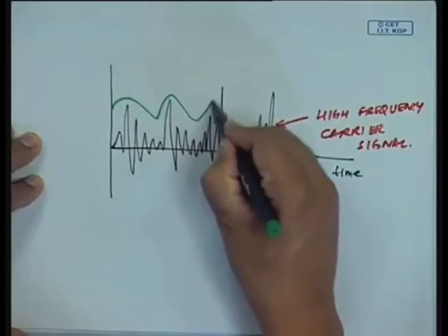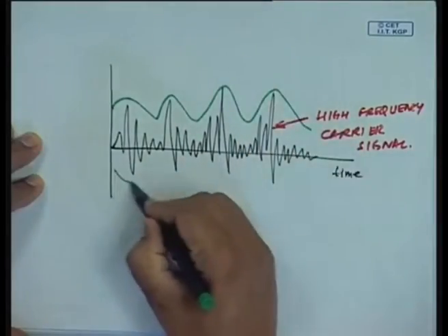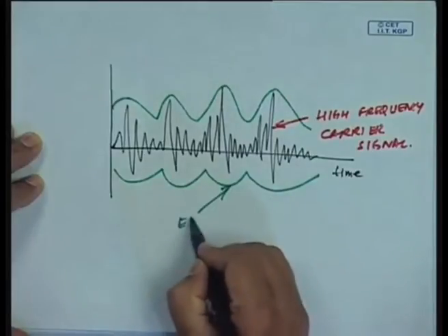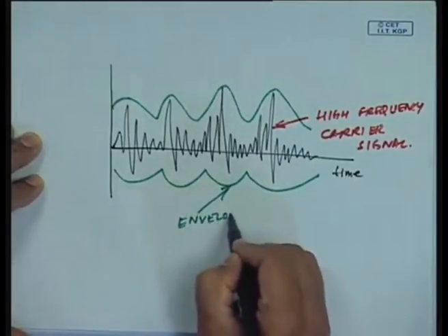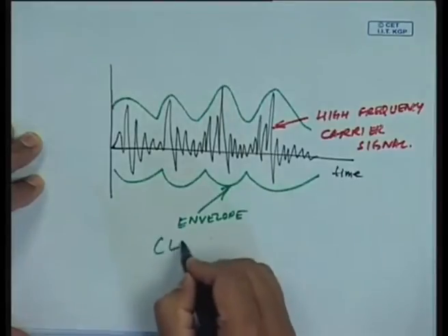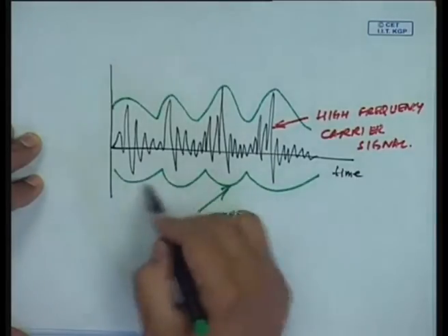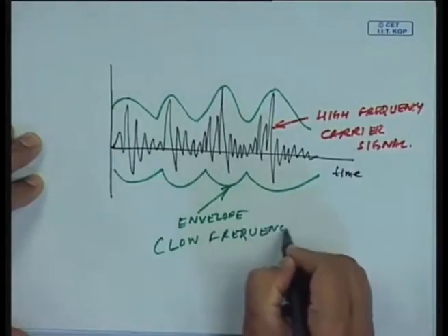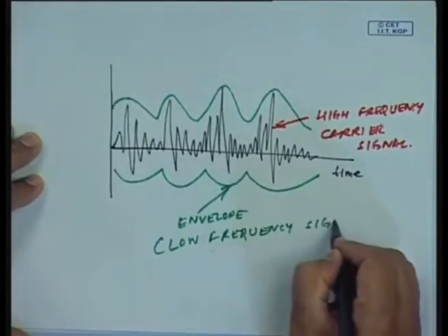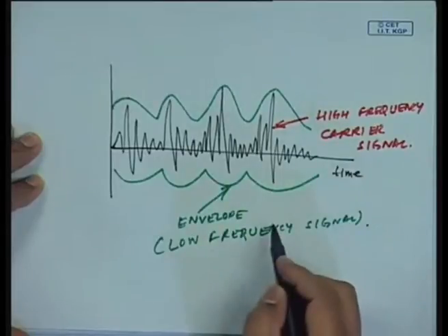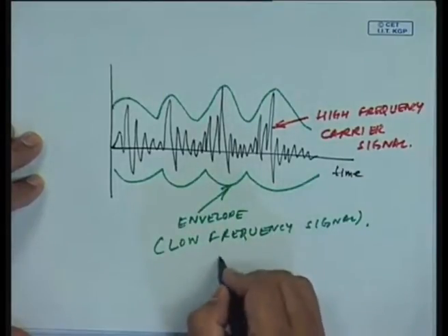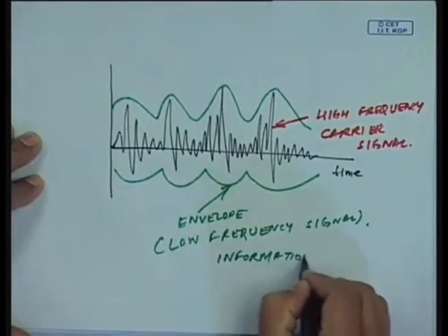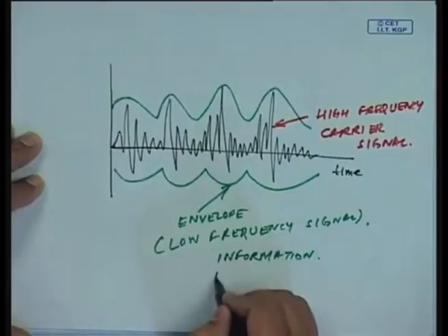If we look at this envelope, which is a low frequency signal, as you can see from the time period, it is actually the signal which contains information, which will be useful for machinery diagnostics.